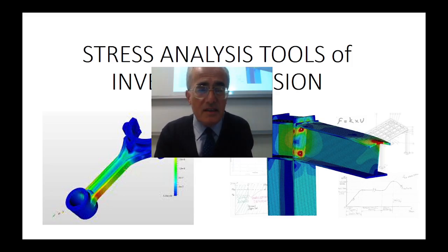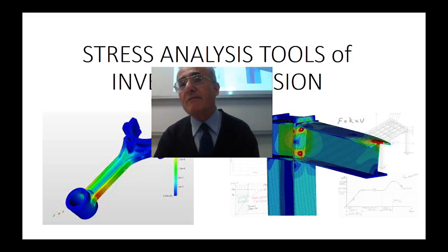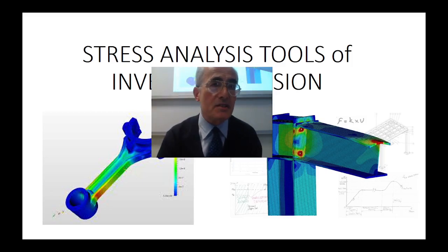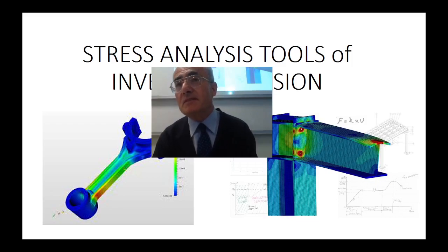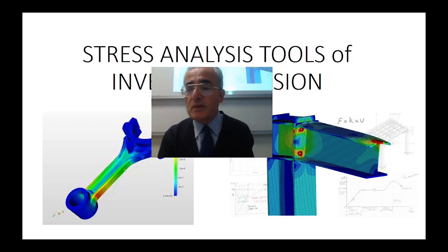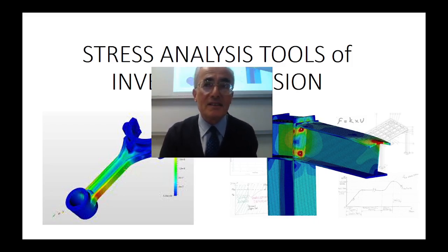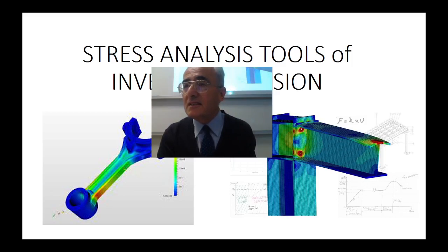In such a case, in Inventor, we have two alternative facilities. One of them is known as the local mesh control facility. The other one is the mesh refinement technique and the corresponding facility. In the content of today, I want to talk about both: local mesh control and mesh refinement techniques.